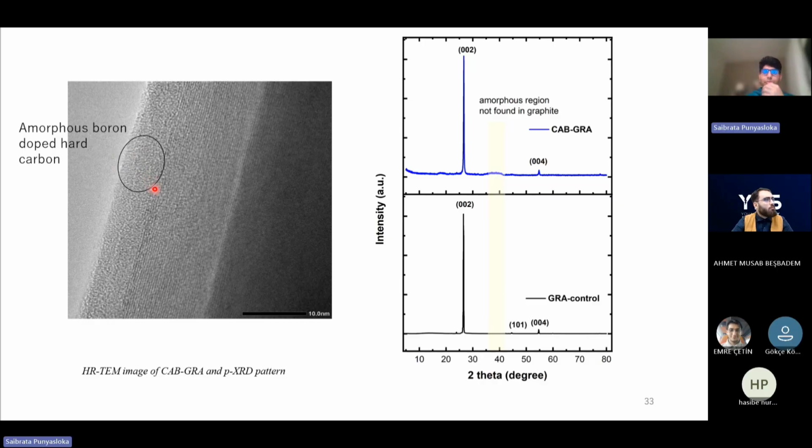This is an amorphous polymer, I'm pretty sure about that. Once you pyrolyze it, the method I followed for pyrolysis gives an amorphous carbon. So you can see this is amorphous, and this is graphite. You can see it's very much stacked, which is one of the characteristic features. So you have two different layers, and this is what shows the coating has taken place.